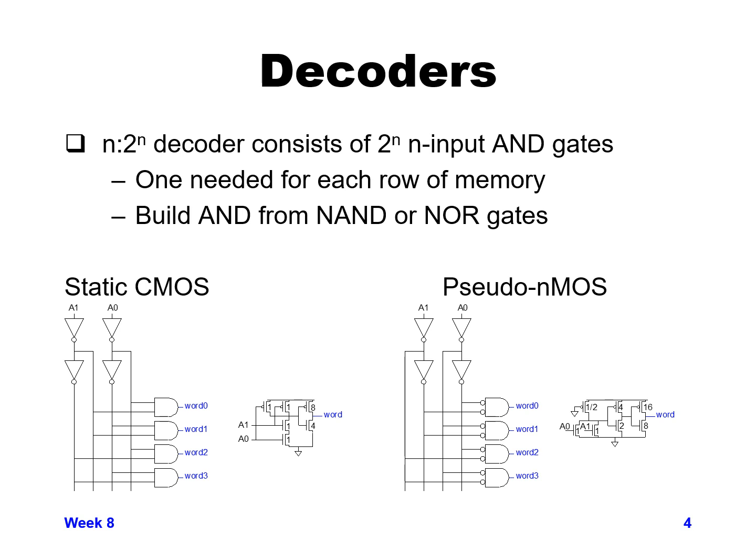So if we have our NAND gate driving that inverter, the inverter can be fairly large and not load down the AND gate as much as the word line would load down the NAND gate. So having a 2-stage function there helps us have the inverter driving the word line.